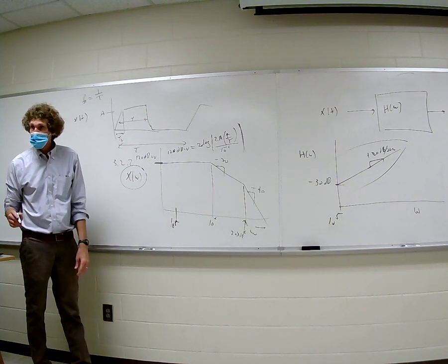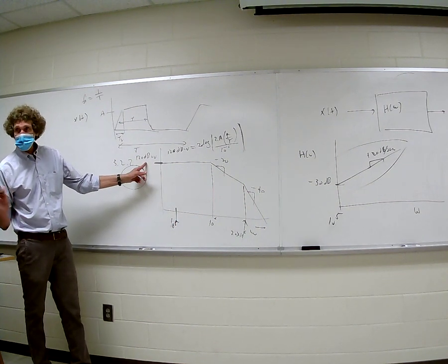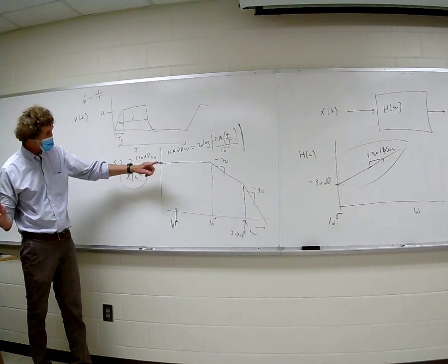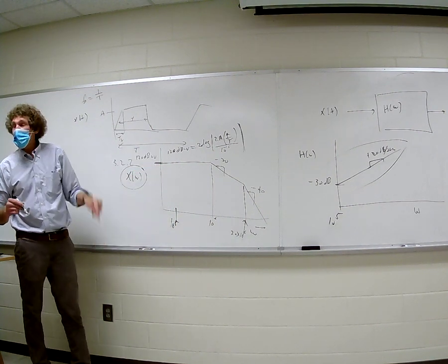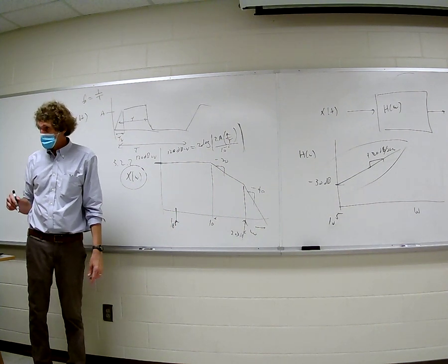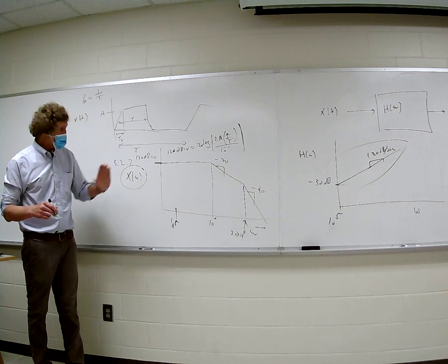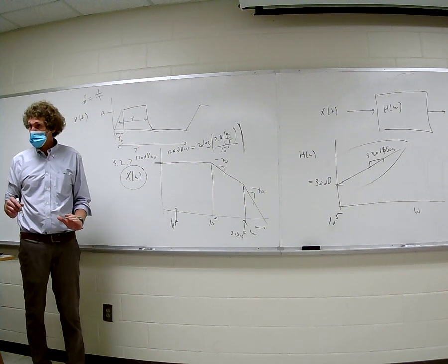Agreed, class? So I start at 10 to the 5th, I've got 120 dB microvolts. Now listen, you agree with me? That's what it is forever down that way, right? 120, and I got to subtract minus 30, so I have 90 dB microvolts. Do you all see that? Right? 120 minus 30 is going to be 90, correct, class?